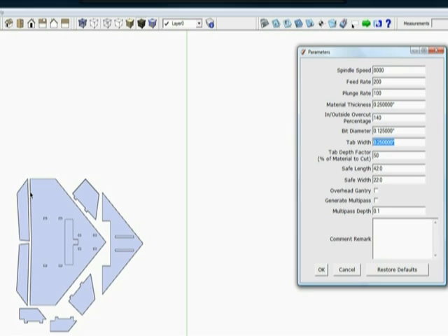It'll jam up the machine, it'll stop, you'll ruin a piece of foam, and you'll never get an airplane out. So what we do is we put in little tabs, and tabs are, in the printing industry, we call them nicks in the printing and packaging industry, because they're basically little bridges, little pieces of foam that are not cut that hold that part into place so that it can't fall out of the rest of the sheet. And of course, when we're finished cutting out all of our pieces, we can go in and just pop the pieces out, or perhaps we'll use an X-Acto and just trim, real quickly, those little 1/4 inch pieces of foam away.